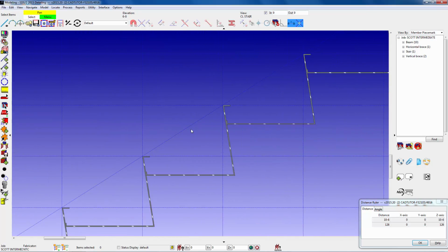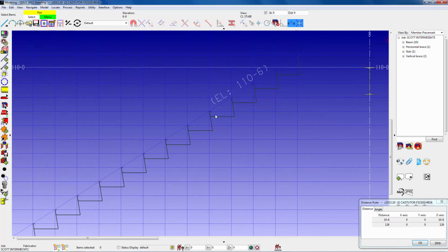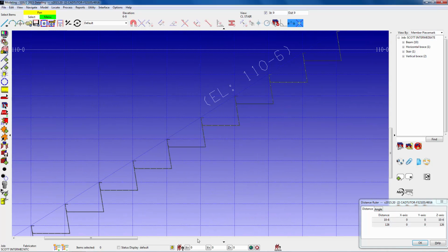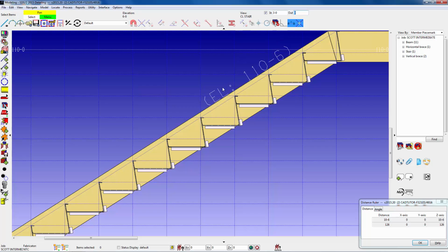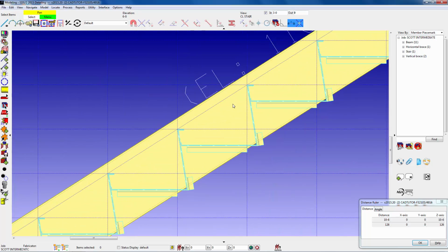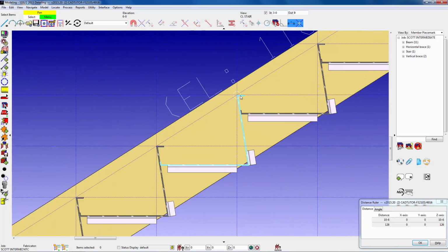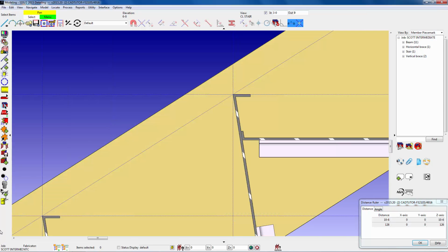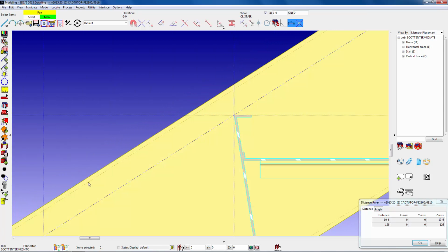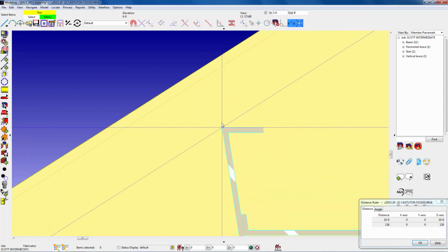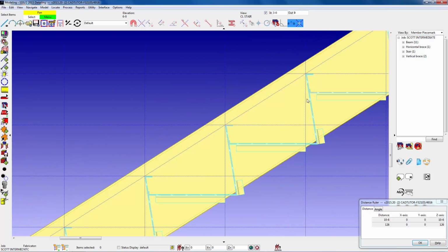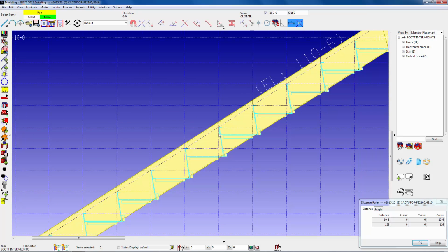And I'm going to zoom in here. And my depth is set to 9 in and 9 out. So my depth in, I'm going to change to 36. And my out, I'm going to leave at 9. And as you can see, my stair came in. Every nosing ends up at the intersection of my construction lines that I put in. So that tells me my stair is input correct at my 7 and 11.